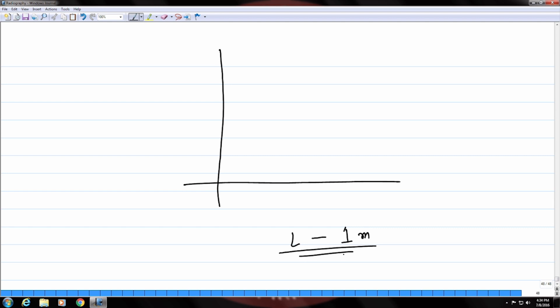So, this chart is in between this exposure chart or the exposure plots that you have. It is in between the exposure. So, this is in terms of times the current into the exposure time, and this has to be calibrated for a particular material against the thickness.